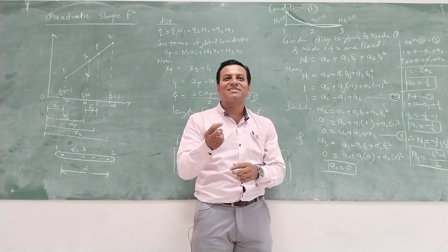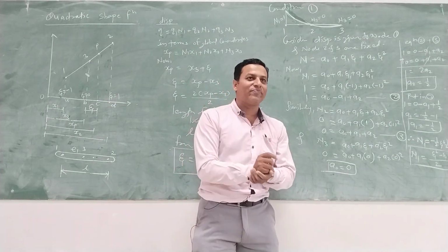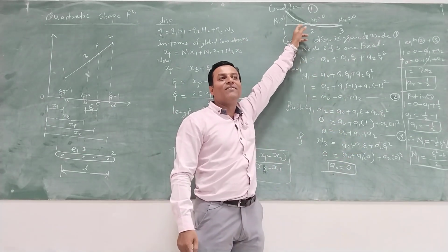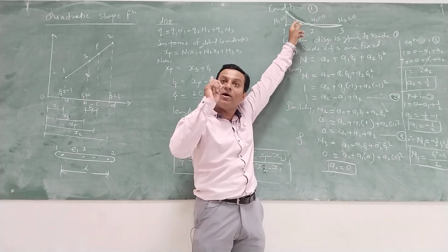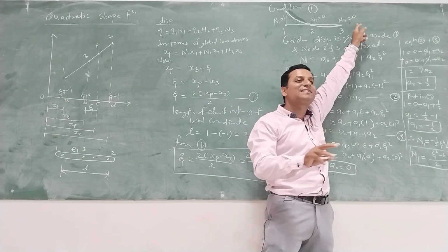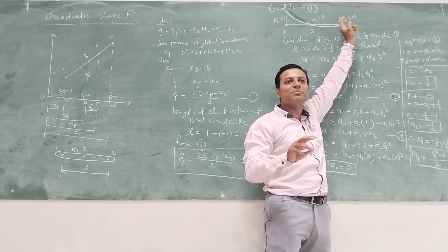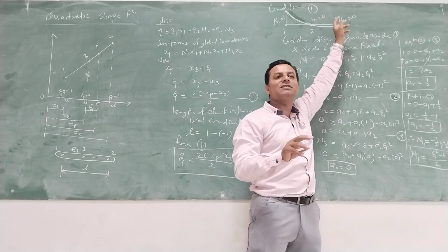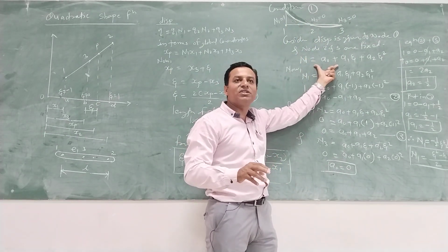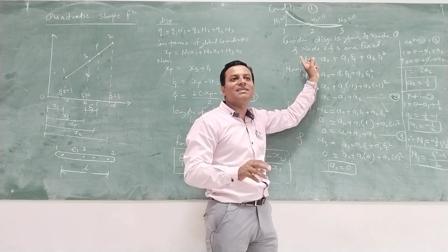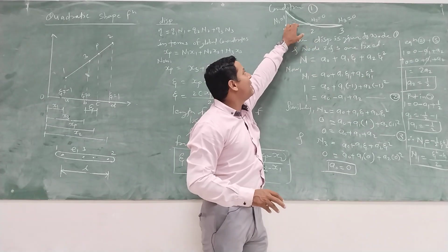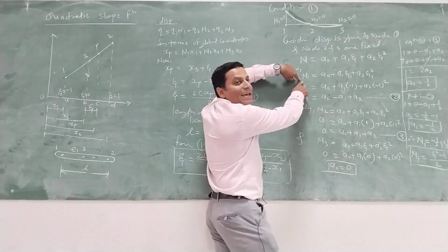Let me tell you in a minute what I did, then you tell me the next answer. See, to determine this one I have taken one condition where I have given displacement to node 1 only, and node 2 and node 3 are kept fixed. Understood, so what is their displacement? 0, and displacement is given to only node 1. I have written the quadratic shape function. Quadratic shape function means N is equal to a quadratic equation. Then by using this condition I have written N1.